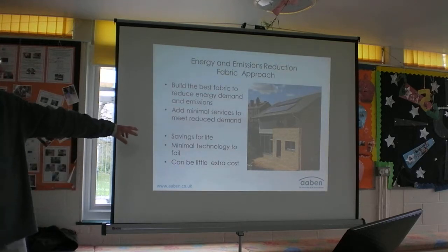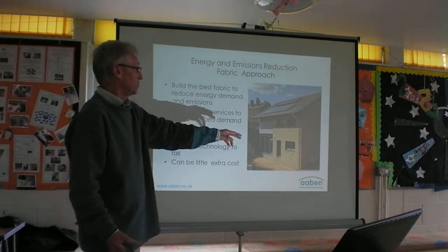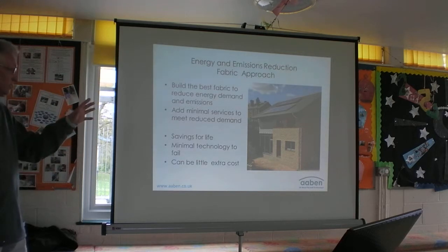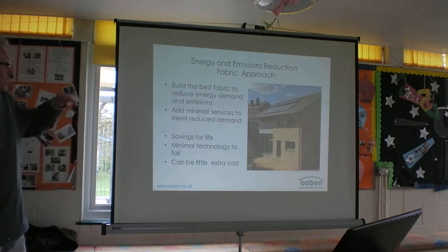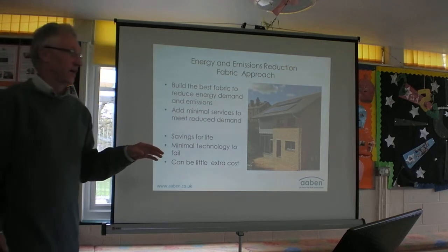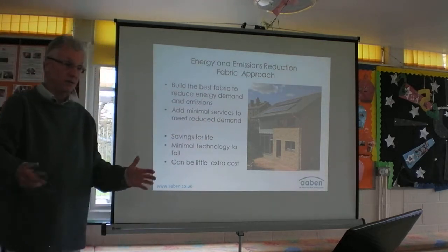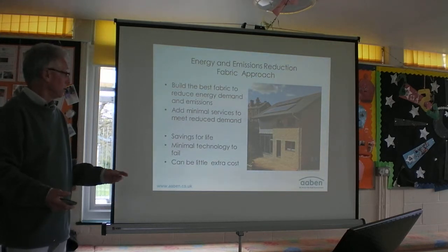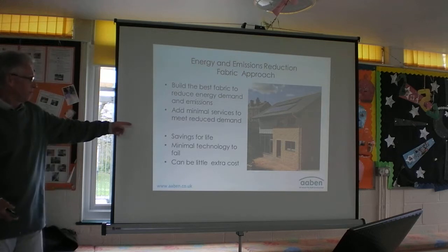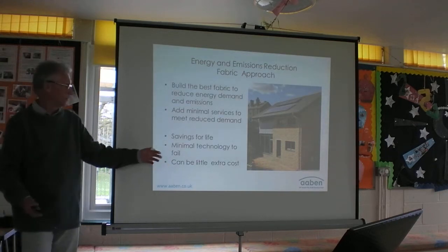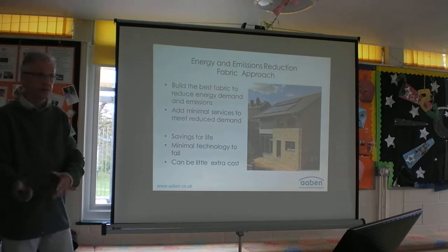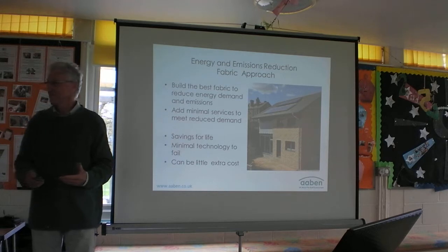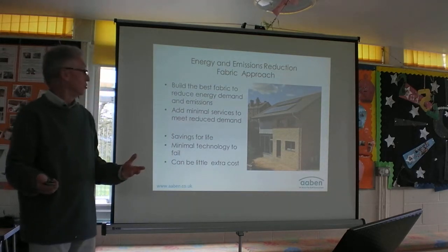That is Denbydale Passive House. Third passive house in the UK, masonry construction. Doesn't look particularly different from a lot of other houses around it. Slightly more modern. You then add the minimal services to service that house. So you've already reduced the demand. You don't need as much kit anyway, and you just put on what you need. You're building savings in for life, you haven't got lots of technology to fail, and the extra cost on fabric may be quite small, okay?